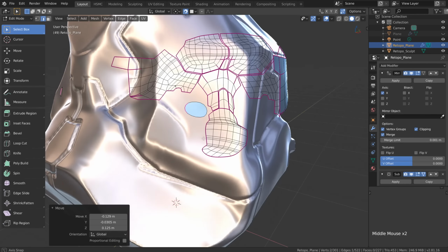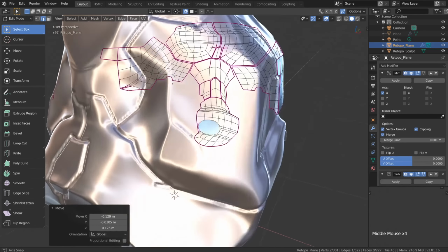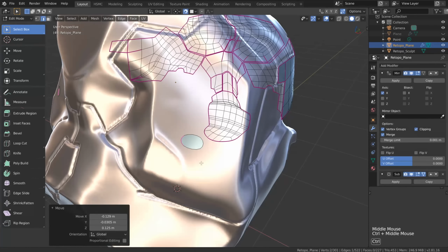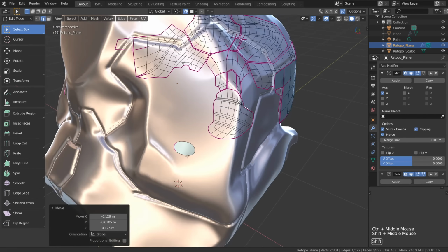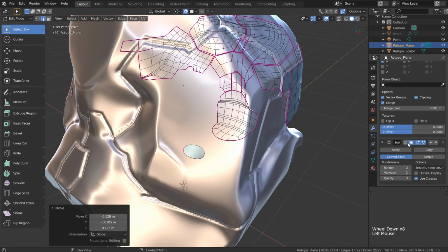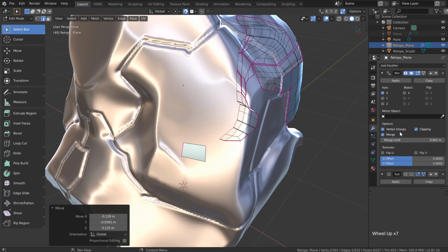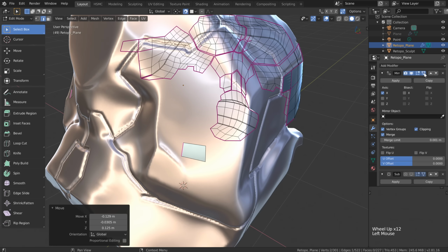Now as you can see, this is where our original retopologized mesh might start getting in the way. Well, I'm perfectly happy with what I can see there. That's totally fine. But let's just take a look at a few more options which can help with this. And also, I'm going to turn off the subdivision surface modifier, just so that it's clear what we've actually got. So we're missing the mirror modifier over there. So I'm just going to come up and enable all of these options here just to make sure we can see its effects there.